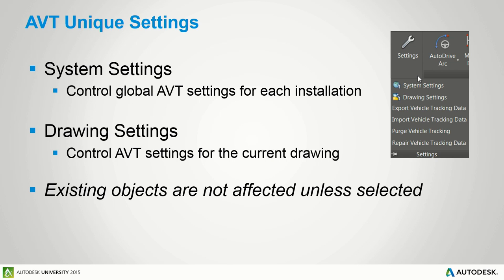And you will see it mainly with roundabouts, where again a roundabout can be done only in 2D, but this is most probably not enough, maybe at some very preliminary stage of design. Then you want to create all other components like corridors, and then use the swept path analysis on top of that. So really the biggest advantage is using Civil 3D. And in fact, you can also install vehicle tracking on top of MicroStation.